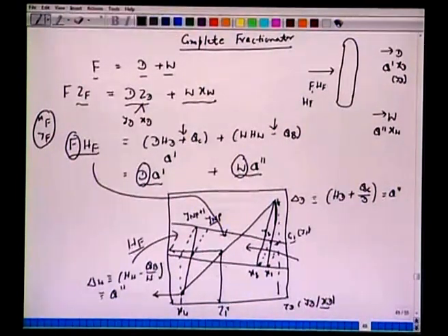And if we want to mark this feed, if you know the composition of feed and enthalpy of the feed, we can draw a straight line between the two, realizing that we are applying mixing rule here, it has to be a straight line. Feed can be saturated liquid, it can be saturated vapor, or it could be a mixture of this, or feed can be cold, right?